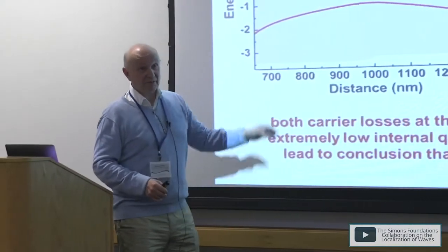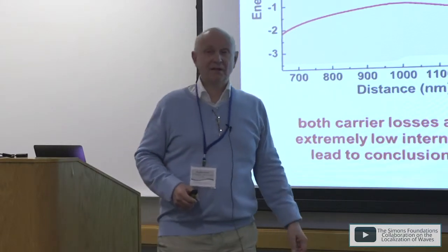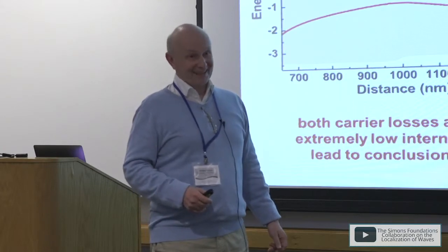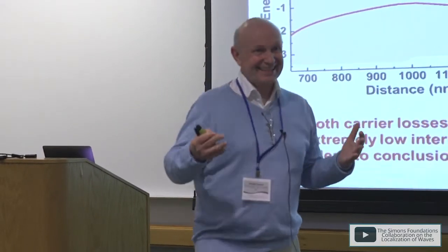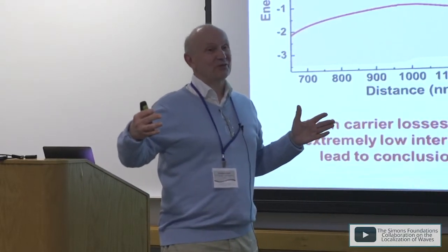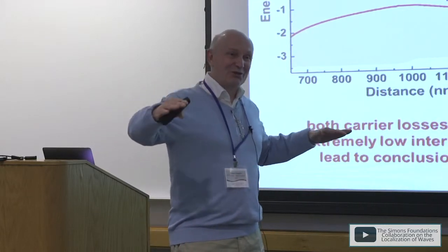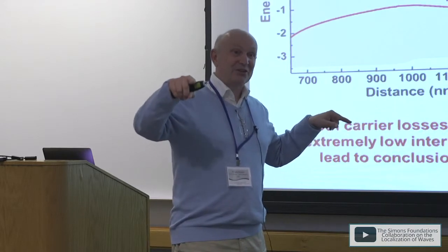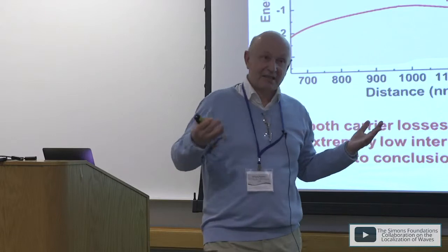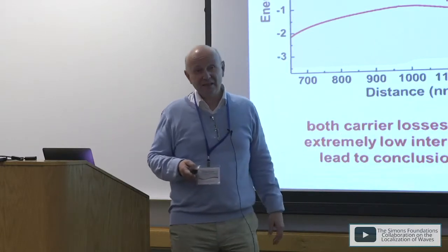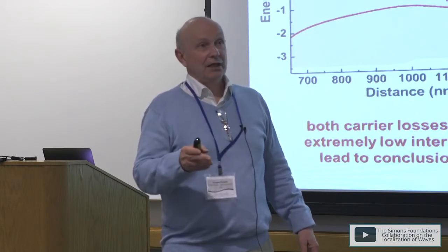In the band, and the same for holes. But this is very specific to nitride diodes and recombination parameters. I think it is specific for thin devices, because if you remember the Shockley paper on the pin junction, the dimensions of the pin junction were hundreds of micrometers. In this case, recombination was strong enough to recombine all the carriers. There were no particles coming to the ohmic electrode, and there was no leakage. But if we consider realistic devices, which have a thickness of a few micrometers, leakage may be very pronounced. But in some of the old InGaP or GaAs diodes, they were LPE grown. You can actually get thick diodes with high-quality material and get efficient recombination from minority carriers.